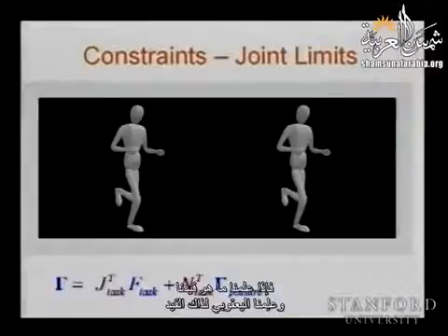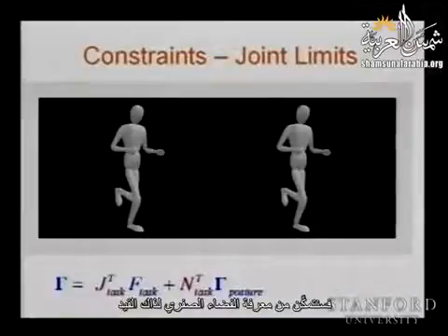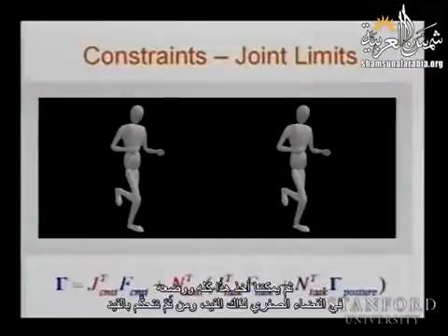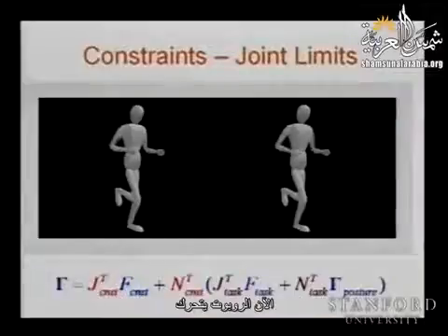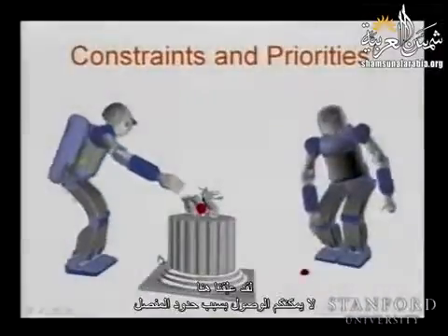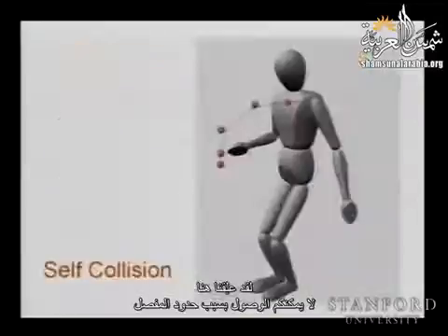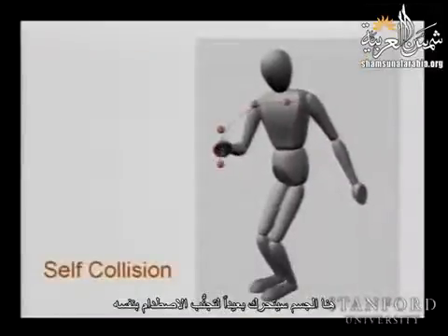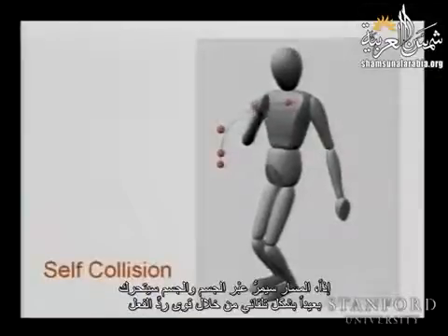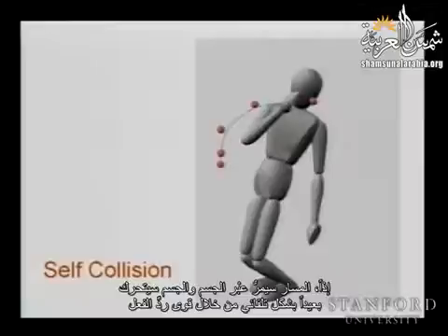So if we know a constraint, and we know the Jacobian of that constraint, then we can know the null space of that constraint, then we can take this whole thing, put it in the null space of that constraint, and then control the constraint. And now the robot is moving, and you can see two different postures because you have hip limits. Here you are stuck, you cannot reach because of joint limits. Here the body is going to move away to avoid self-collision. So the trajectory is going through the body, and the body will move away automatically by these repulsive forces.